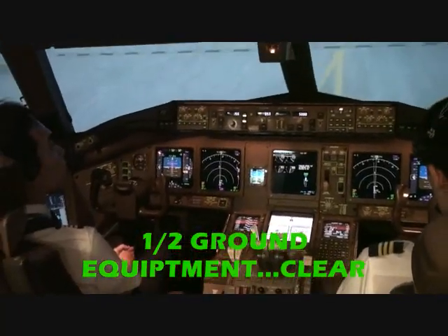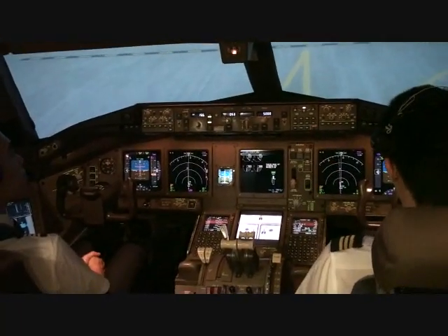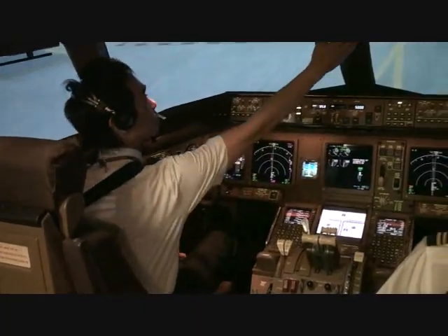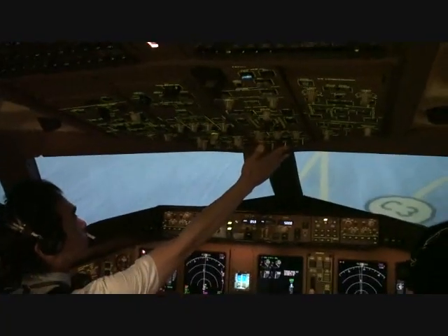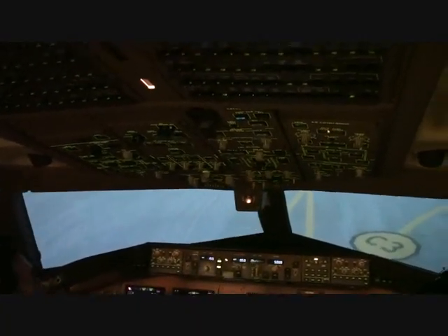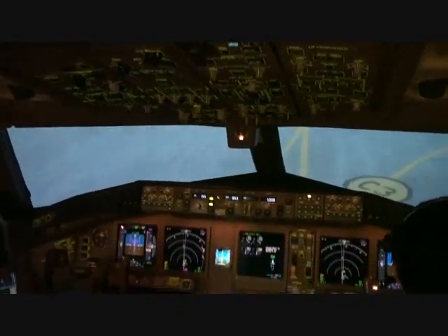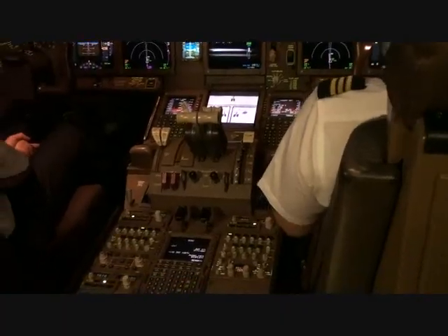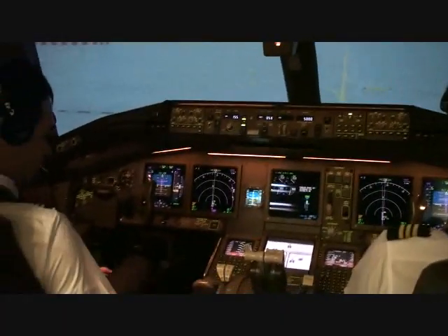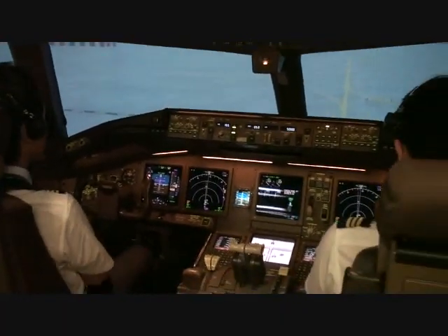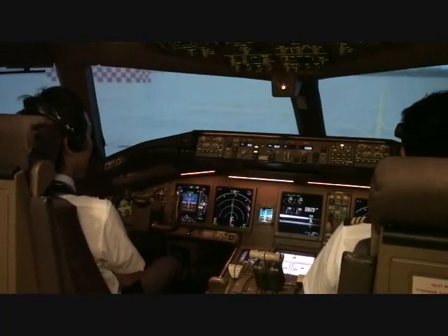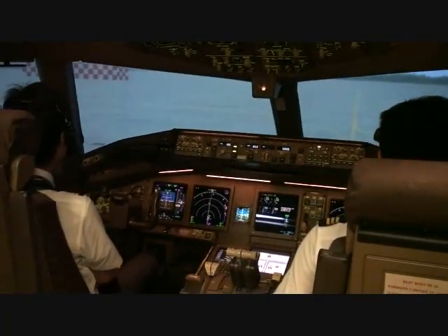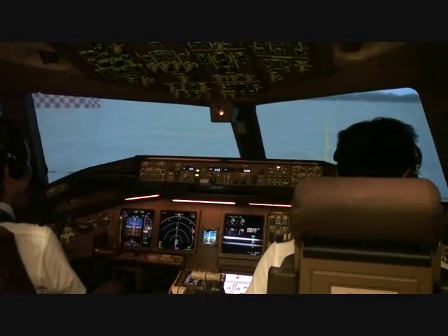Ground crew signal received by both pilots. View the OK signal and steering bypass pin if used. CM1 signals the ground crew. Inside right side clear. Taxi clearance received. Request taxi. Roger. EVA Trainer 1 request taxi. EVA Trainer 1, roger, clear to holding point runway 05 right.